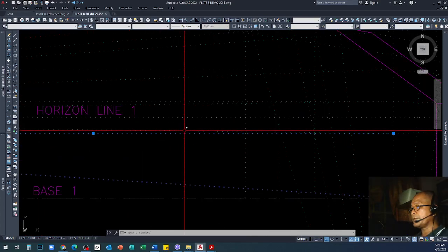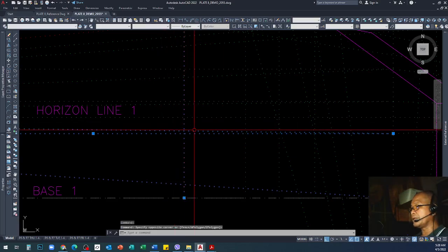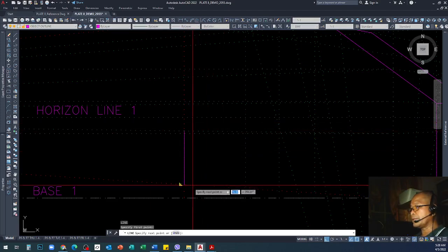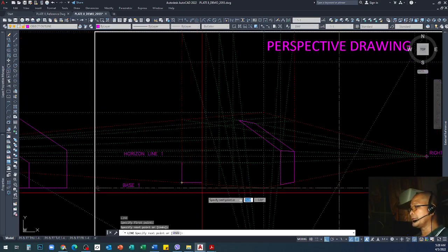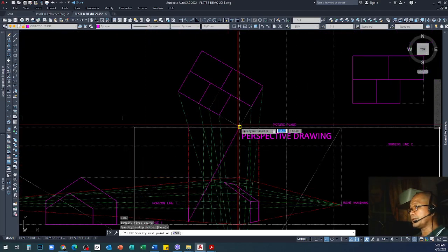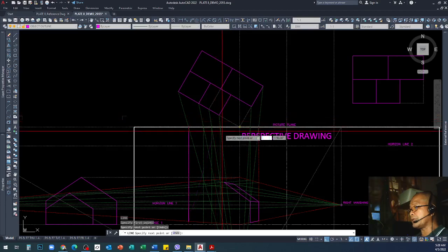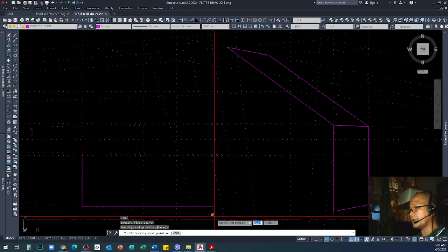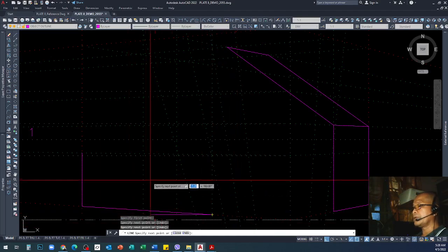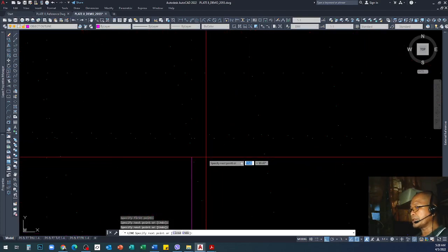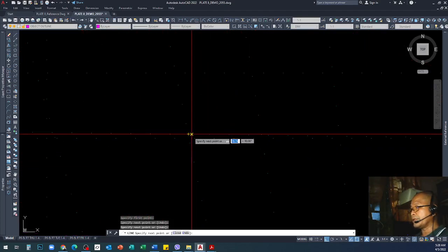So the height of your object will be here, the intersection of this line and the red one. Okay, so I will draw a purple line, or magenta rather, and then this portion here we already projected, which is this one, and bring it down to the intersection with your red line, this one. So we know the height of the other side, which means it will also be here.